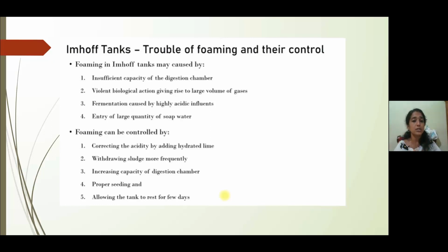Then fermentation caused by highly acidic influence. If the condition is acidic, fermentation can happen, and it will also cause foaming in the digestion tank. Entry of a large quantity of soap water: if the wastewater contains a large quantity of soap water, then also foaming will happen.